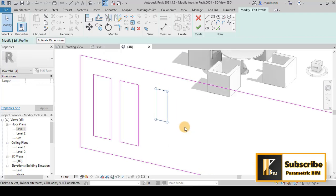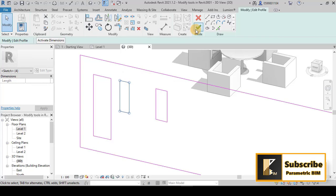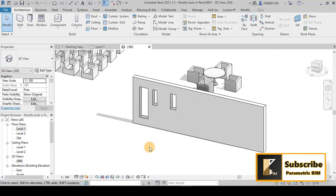So this is the graphical, but if I want to make, for example, scale of the here by numerical and I know the proportion, maybe I want to make it by half, so I will click the base point and it will automatically go and make it like that. Also you can bring any image, and by the same way you can make scale. So these are some applications of scale.